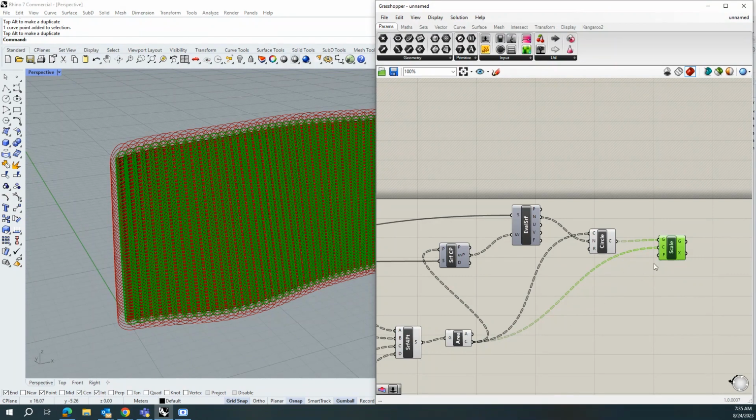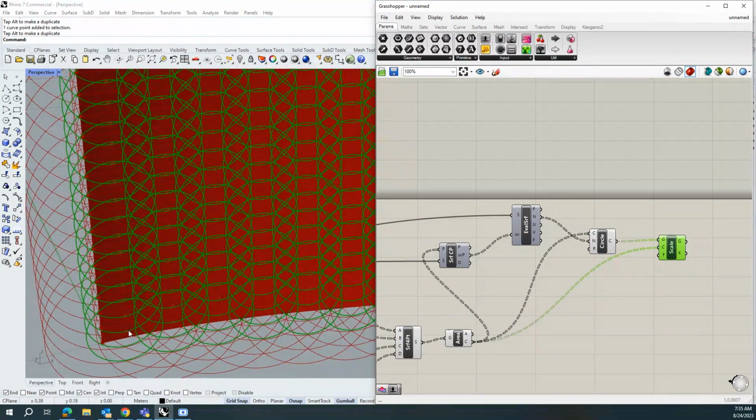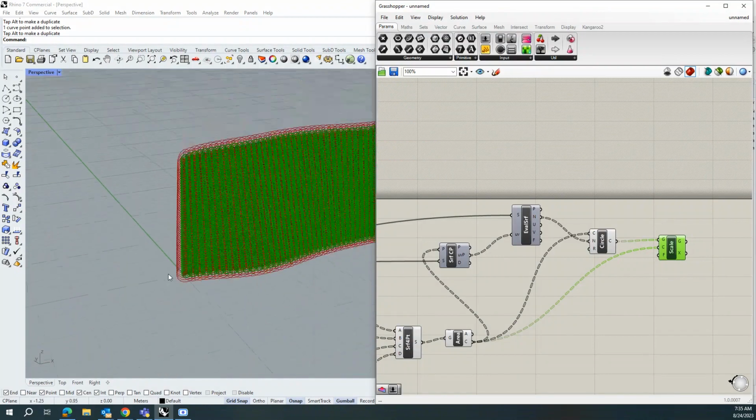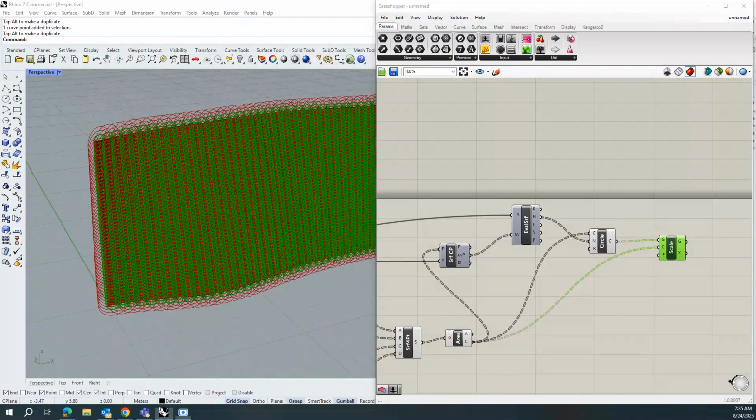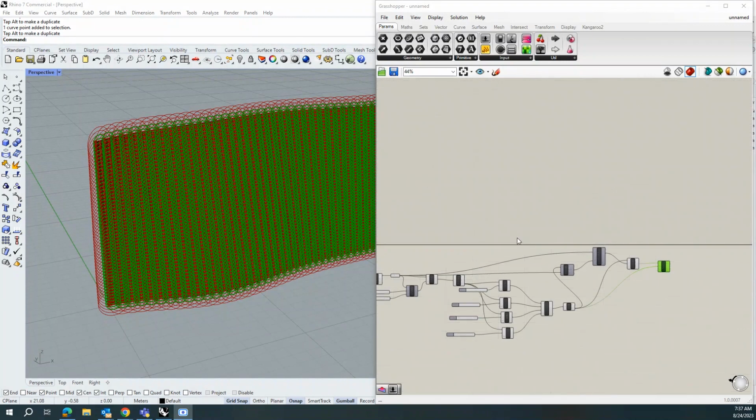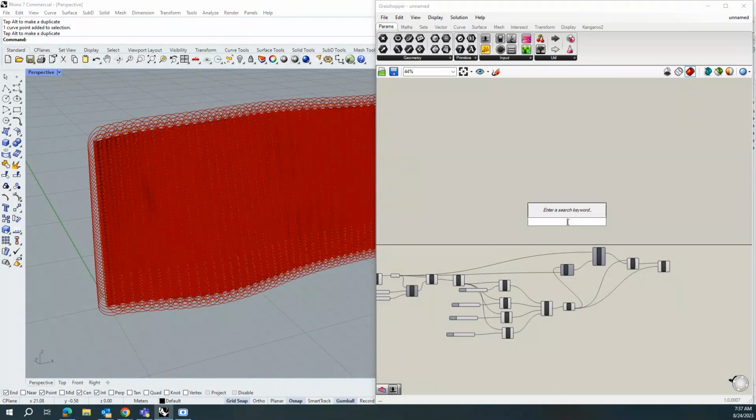Once you have created this scale, it will take the default factor of 0.5 and scale down the original circle. So now we have scaled the circle, but we do not want the regular scale down of the circle. What we need is the variation in the geometry for each of the surfaces. So what we can do is create a component called curvature.